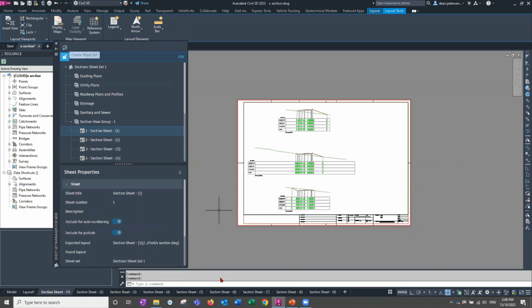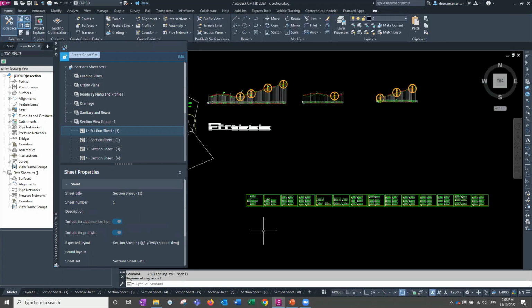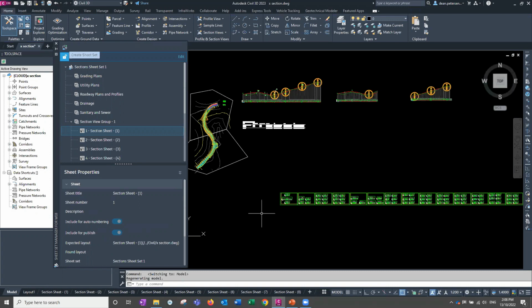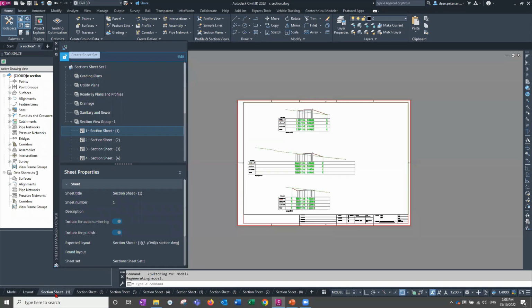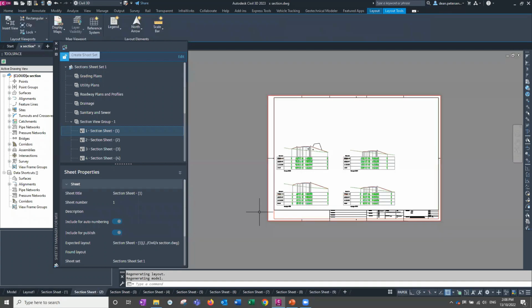While we've got this open though, this is my drawing that's up on the cloud-based drawing. There's my model space. Now, you'll be familiar with the time it takes with a drawing with cross sections in to do a regen. So to open my model space there, it took a little while. They have been working on the regen time of the layouts, which is actually dramatic. So if I click on sheet 2 here, which I haven't yet opened yet, there it is. Sheet 3, there it is.